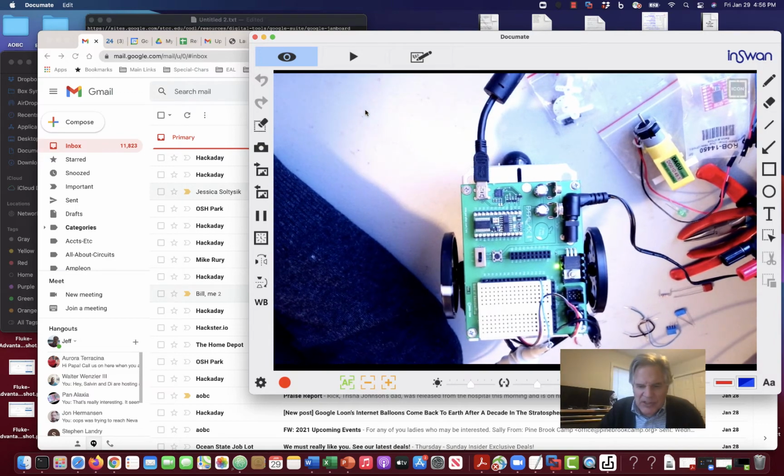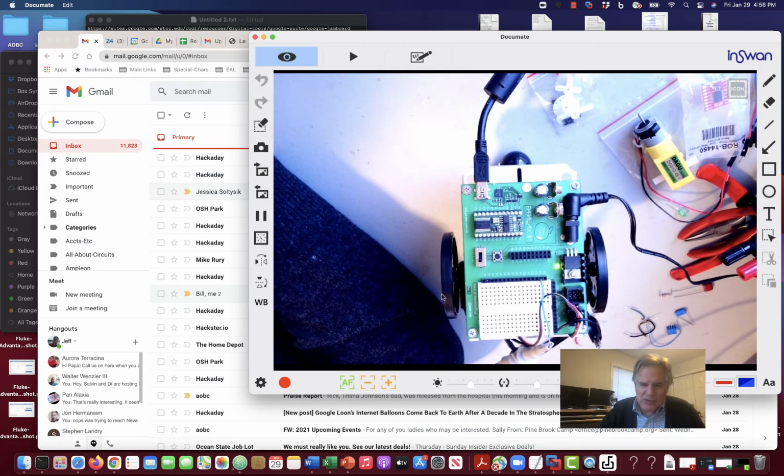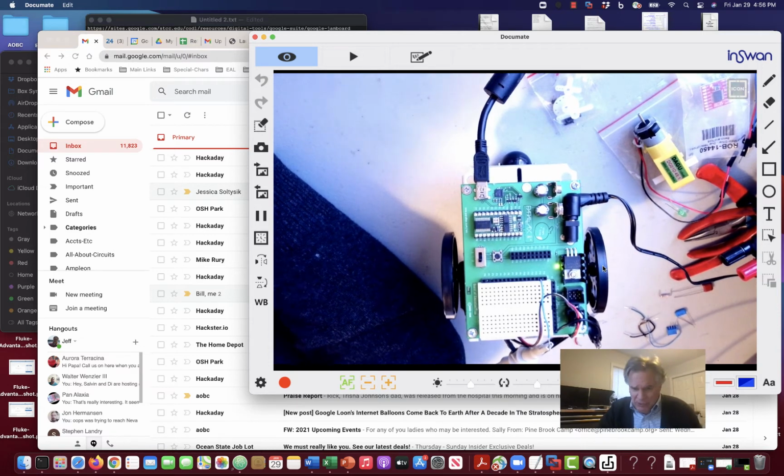And you might ask, how is this a servo motor? The thing that is servoed in this case, and it's not servoed especially well, is speed. This is not a positional servo. This servo is more of a speed controlled motor. If you try this with different motors, if you remember from your Bobot, you needed to actually tweak things a little bit to get both motors rotating at the same speed so your Bobot would travel in a straight line. But there is some sort of reference inside the little motor box, and when you give it pulses of a certain size, it will rotate at that speed.